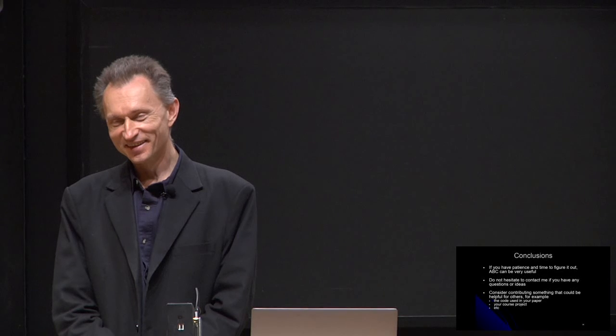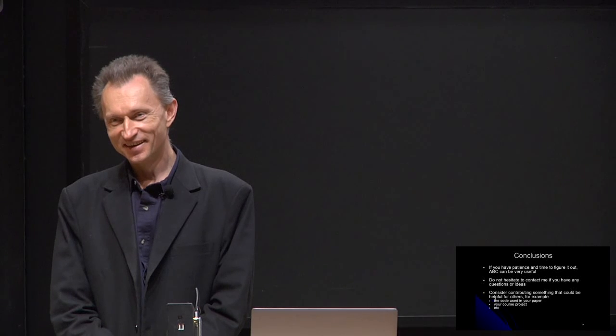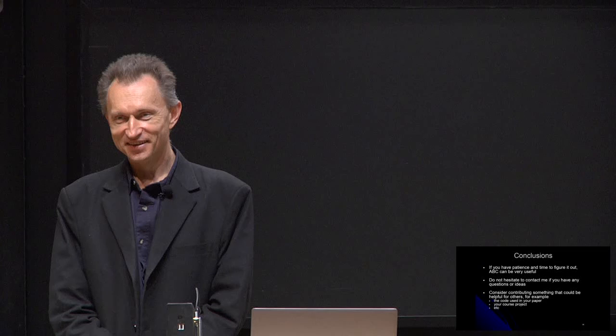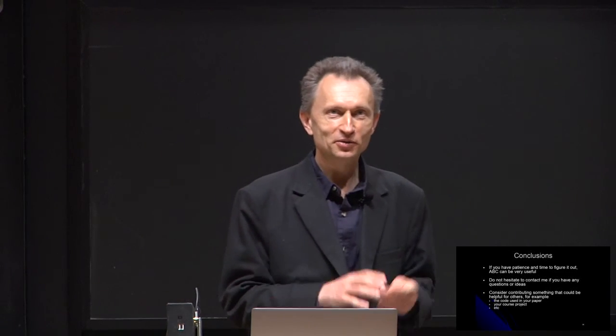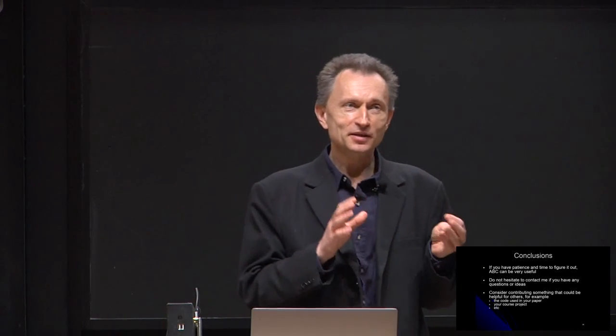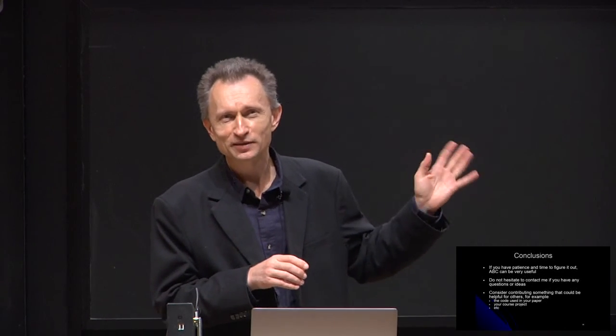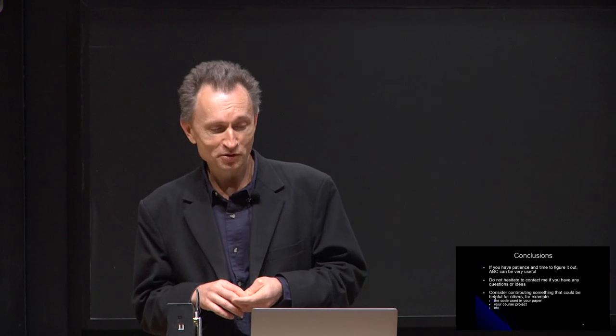Okay. So when you say a node, is that kind of equivalent to an AND gate? So how large a design, do you know what a large design is that someone has used ABC with? Okay, so it of course depends what the usage is, because people use ABC for so many things. I would think synthesizing a design block, like a sequential or combinational design block with 1 million gates, which would roughly correspond to 1+ million AIG nodes, is doable. Runtime may not be good, but we also know that industrial tools also have long runtime.